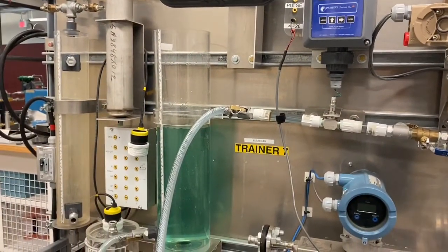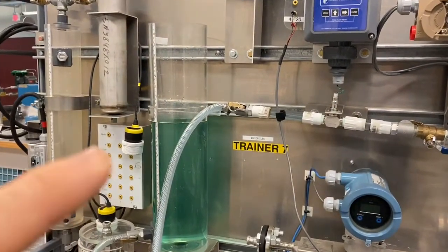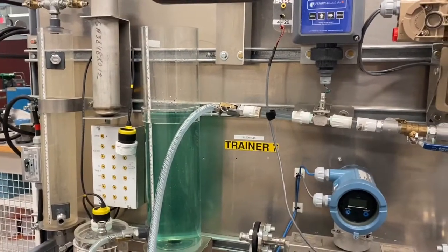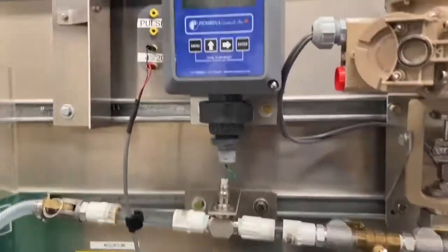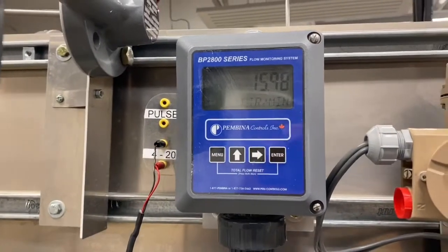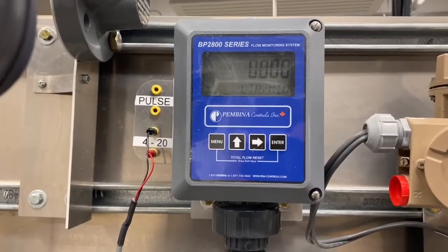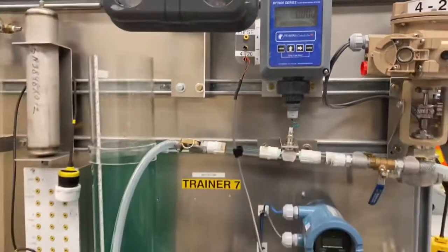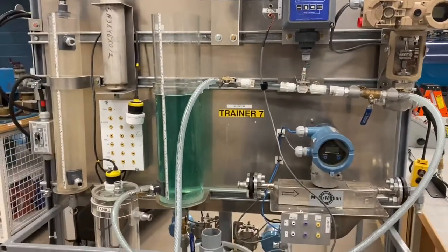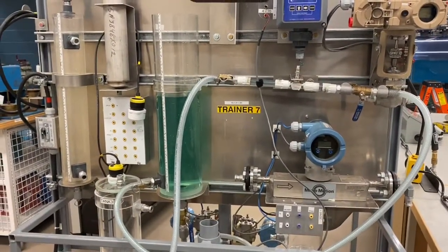And it has the correct K factor now, so it can figure out the flow rate of the liquid into the vessel right now. So I'm just going to go and shut that off, and we should see that drop off to 0 because the turbine's no longer moving there. So there, it did. All right, so that's everything for this lab. Good luck with figuring out your K factor value.